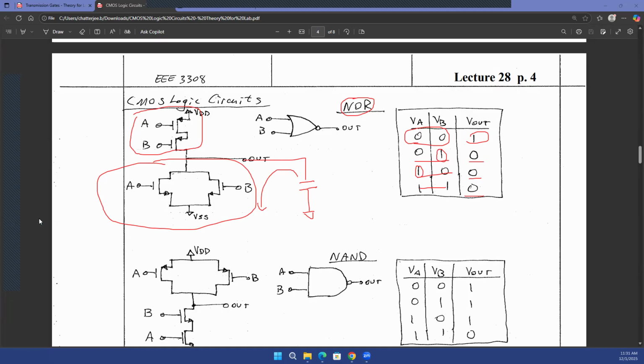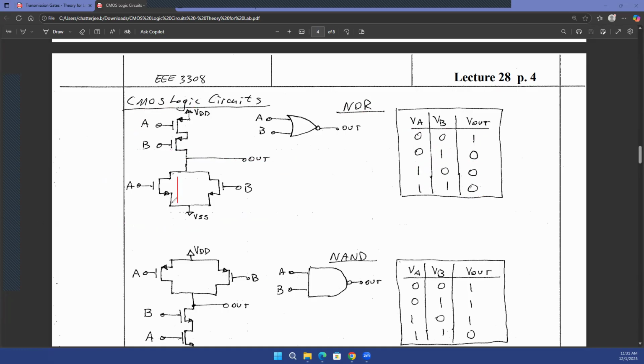And you know that if you put circuits in parallel, current can flow either through the left side branch or the right side branch or both. So to create the pull-down network, you'll just have these NMOS transistors in parallel. To create the pull-up network, you just do the opposite, because PMOS transistors are duals of NMOS, and NMOS transistors were in parallel. You put two PMOS transistors in series. And that's what will complete your pull-up network. Let's stop here. And we'll discuss why your pull-up network has series transistors and the pull-down network has parallel transistors in the next lecture.